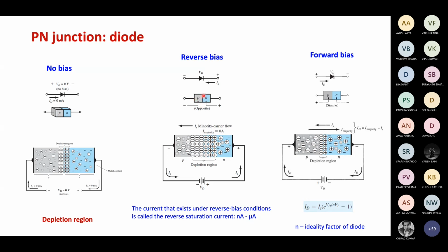That's extremely difficult, extremely unlikely, I would say. There might be defects at the junction as well, dangling bonds, mismatch between the bonds, and because of those non-idealities, this current is affected, and that is accounted for by this parameter N.